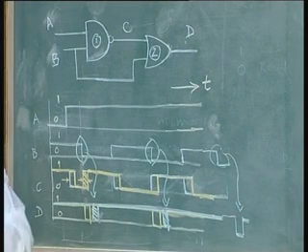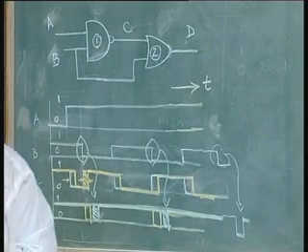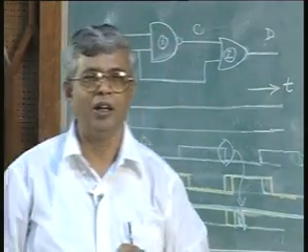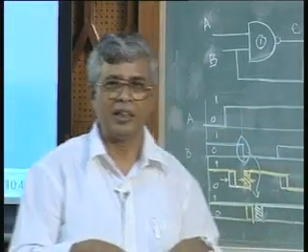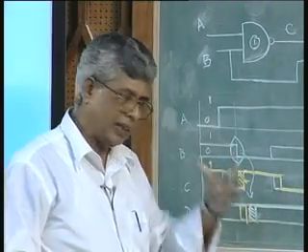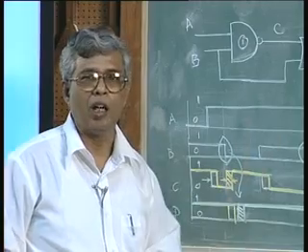The flip flop operation is because of, remember that RS latch we started with, the 2 inverted NOR gates, that should be the one to which the input is considered, all other things are only external peripheral circuitry. So, to that input circuit, the input will change only very narrowly like this. So, this is how an edge triggered operation comes.